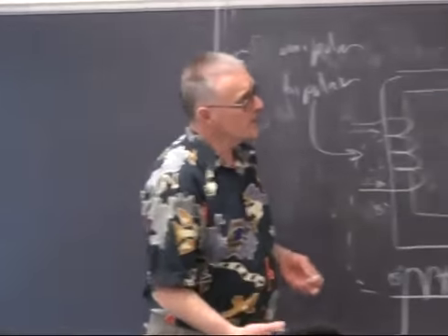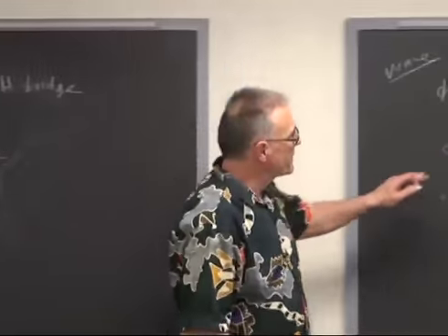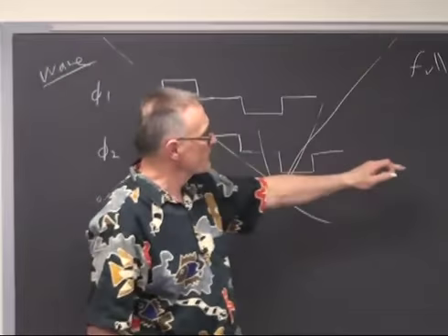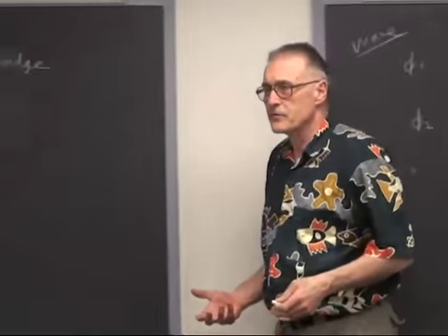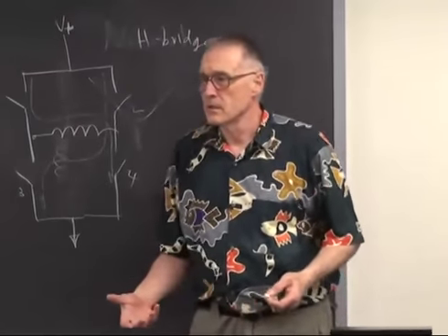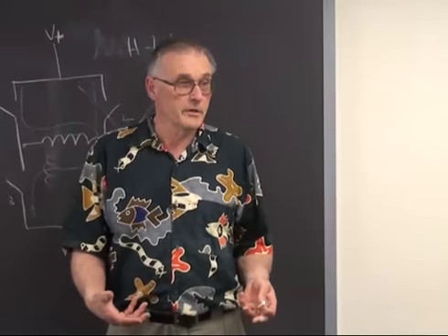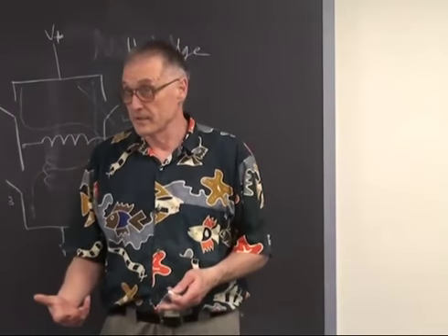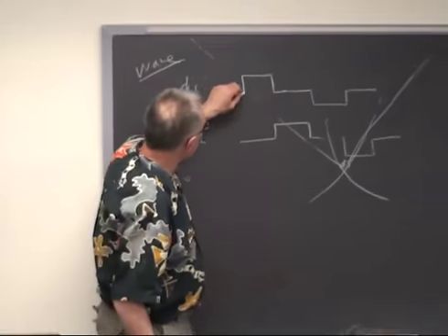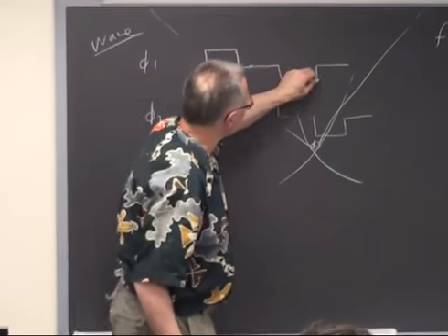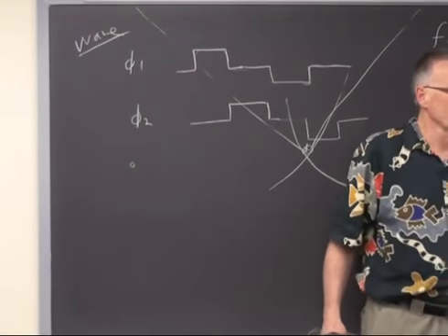So then the microcontroller is going to generate this pulse sequence, probably through some kind of direct digital synthesis. But instead of having a sine wave in the table, you're going to have some sort of pulse train in the table. The table entries are either going to be something that looks like this for one cycle, or something that looks like a square wave for one cycle.